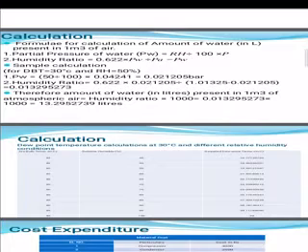I have shown you the formula for the humidity ratio. Therefore, for the amount of liters present in 1 meter cube of atmospheric air, we have multiplied by 1000. According to the data, that is dry bulb temperature is 30 degrees Celsius and the relative humidity is 50%, we have calculated that in 1 meter cube of atmospheric air, around 13 liters of water is present. We can extract that amount of water.